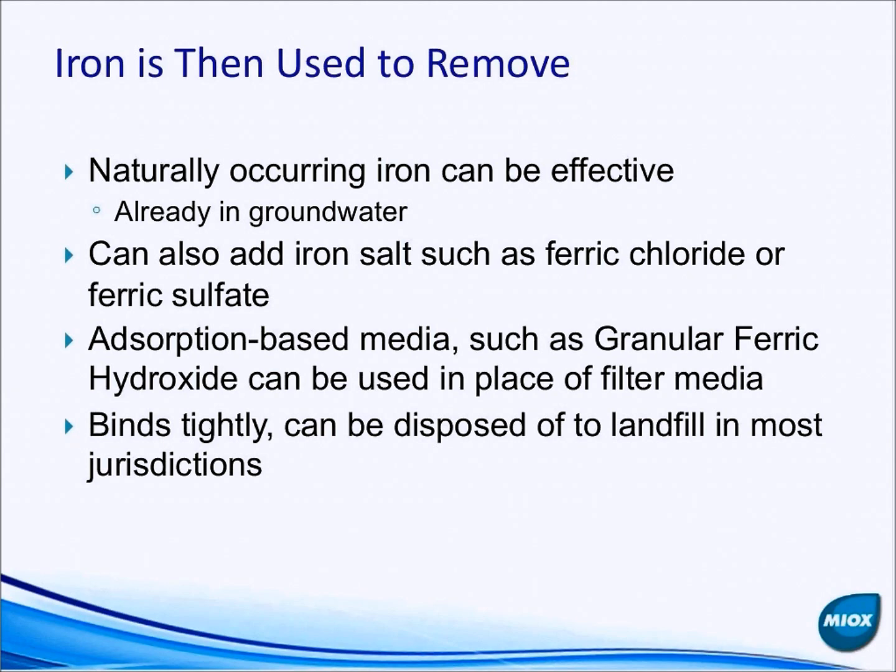Alternatively, there are a variety of iron-based media out there, such as granular ferric hydroxide or other types of precipitated iron media, that can be loaded into a pressure vessel. The arsenic-laden water can then simply be run through that pressure vessel, and it will absorb the arsenic out of the supply.